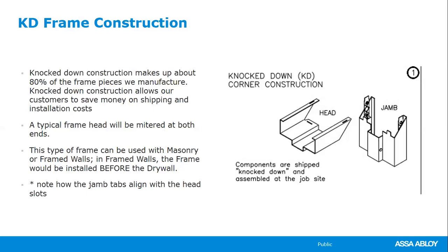And then we also talk about a true drywall frame, and we're going to get into that also, but that type of frame is designed for interior application. Right now we're talking about an exterior type of frame, or a frame that's going into, say, a retail space where you have exterior openings and then you have the frames that are inside that retail space. Those all will be welded type of frames.